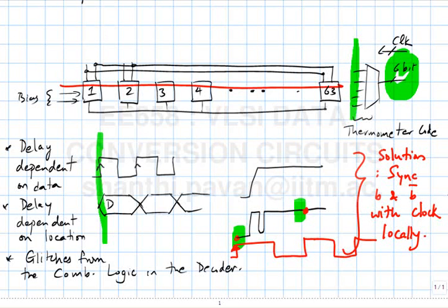So there is clearly dependence on the previous stuff and the present stuff. So the delay, you can never make it independent of state. And even if all those lined up, the moment you route it, you will find that there is still some delay. Definitely not synchronizing the enable signals locally with a clock is just something which will never work.